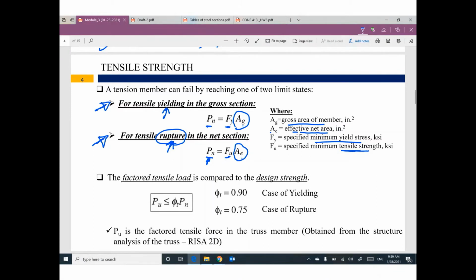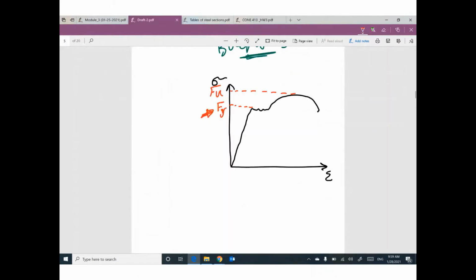I have two questions here, and I'm looking for your questions at this point. What do you mean by nominal strength? We understand this concept, nominal. For nominal, we need to multiply this term by something called a reduction factor. Do you remember phi? If you multiply phi by Pn, you can get the design ultimate strength. That makes sense? Do you remember in the concrete course, we have Mn and we have phi Mn. This one is the nominal, theoretically. This one is the design value.